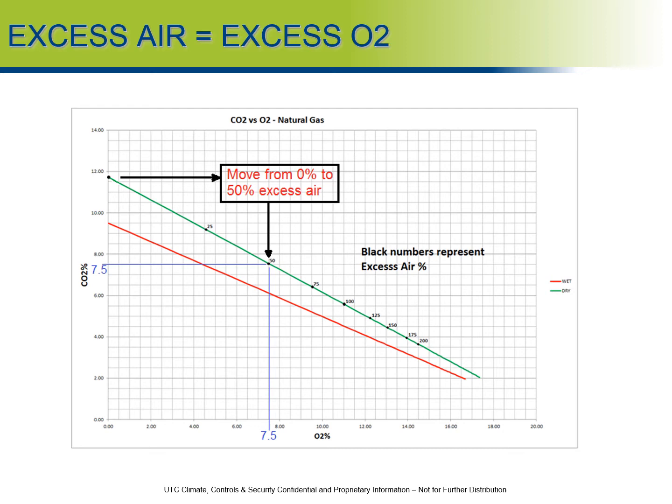So now as we take a look back at our combustion chart, or our CO2 to O2 relationship chart, we can see, looking on this line here, that adding the excess air to the equation brings our CO2 and oxygen levels to a more acceptable level.